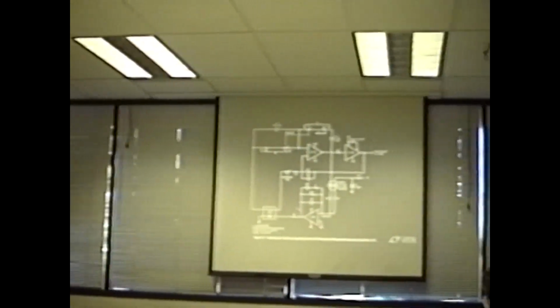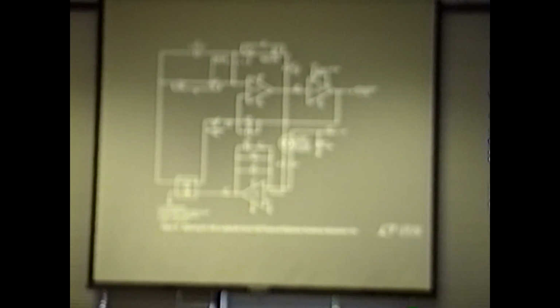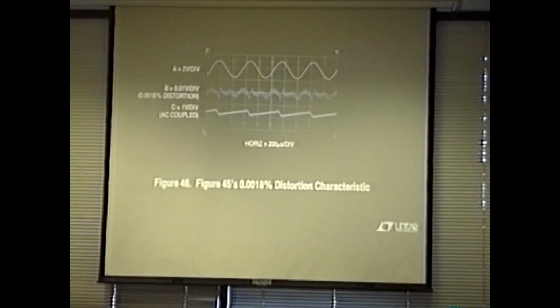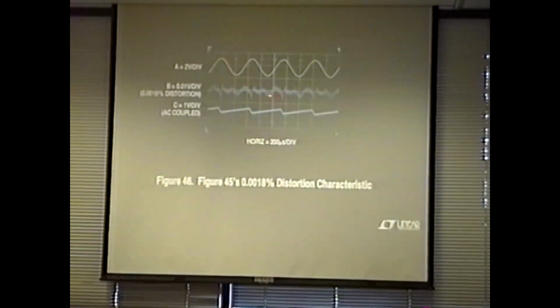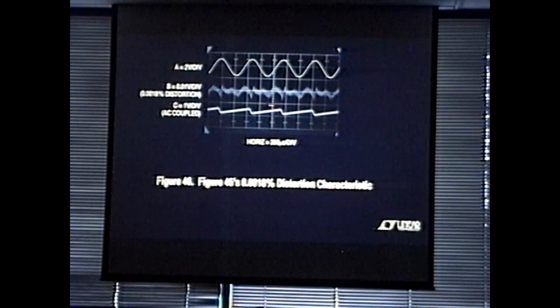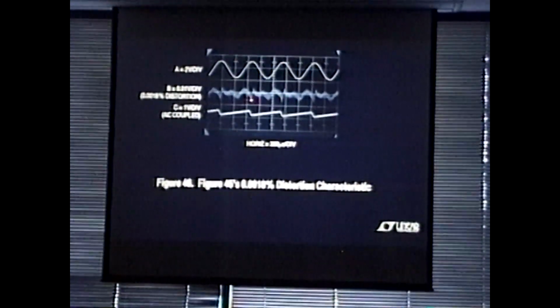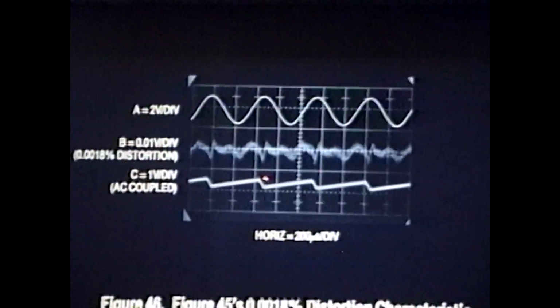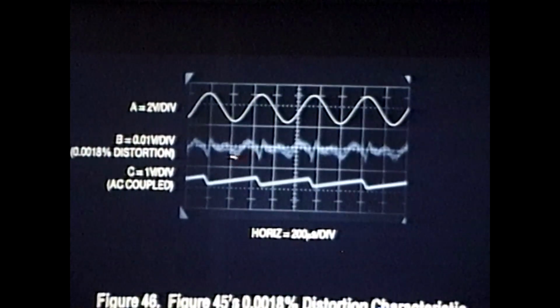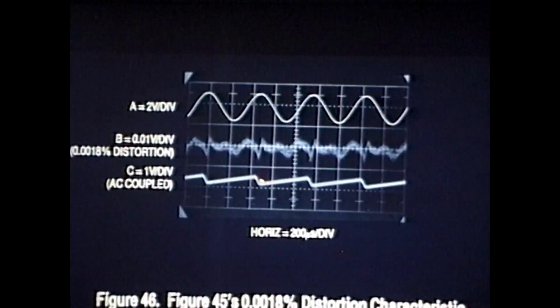This is a very, very simple-minded AGC. You know, because once I figured out the waveforms I kept not discussing in here, this is the AC coupled output of the AGC. And what I concluded was, see the peaks there? Yeah, the AC coupled output of the AGC is affecting the distortion product there. So clearly a fatter time constant is going to help. You want to mush those peaks down. But I was chasing this 2F right there.